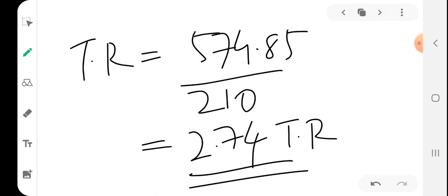So this is how you do problems on this type of vapor compression system. So students, you should be thorough with the thermodynamics, the properties of the fluid: how to calculate the property inside the dome, how to calculate the property outside the dome, that is the vapor dome, how to relate the entropy at the vapor line with the entropy at the liquid line, how to apply the concept called dryness fraction. So what is the process, whether it is isenthalpic, isentropic, or constant pressure. All those things you should be thorough with, then only you will be able to solve any kind of problem. So try to solve different problems.